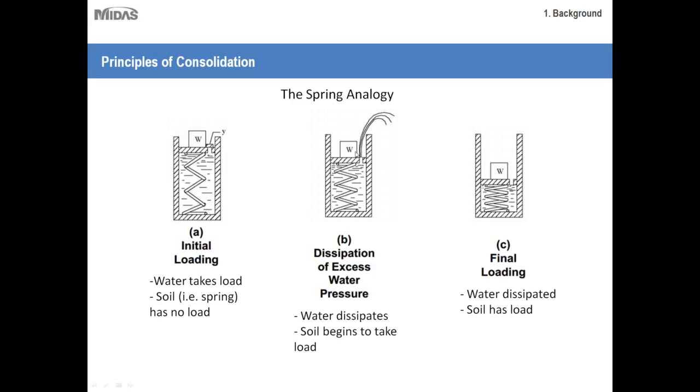So, eventually that valve comes loose. And then, little by little, the water gets expelled out of this encasing here. Or in the case of soils, the water drains to the surface. So as you can see, as this load continues to stay there, it's slowly going to settle until finally the water is displaced completely, and the soil has all the load. So that's an important thing to keep in mind, is how the water and the soil both play a part in how settlement and consolidation occurs.